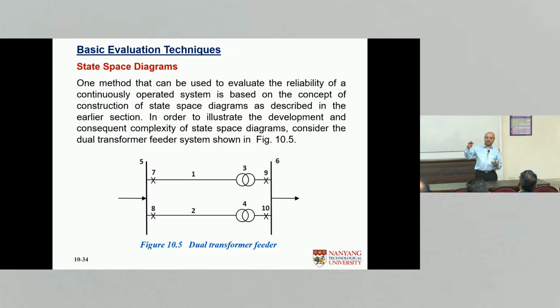And we use the subscript P to say permanent outage. Very soon I'm going to show you another subscript called M, where M is the maintenance outage. We also have some transient failures in power systems, so we can use the subscript T. So you will see lambda PT. That means a permanent outage overlapping a transient outage. Lambda PM, a permanent outage overlapping a maintenance outage, and things like that.